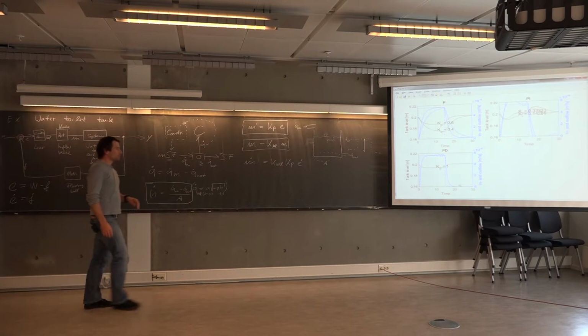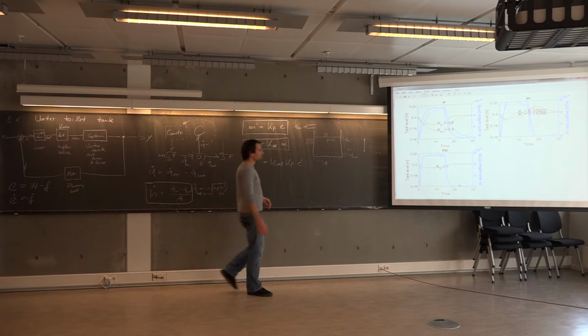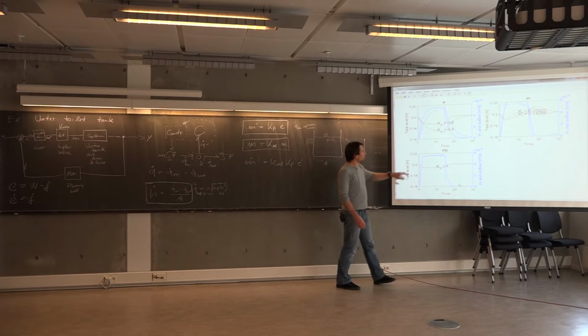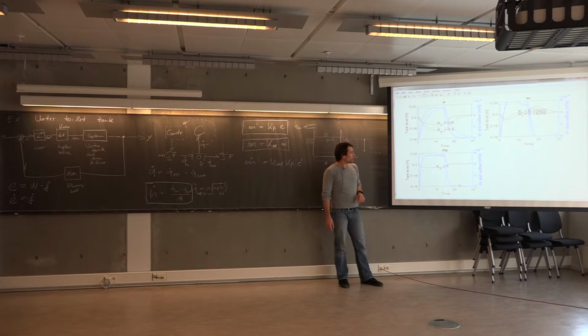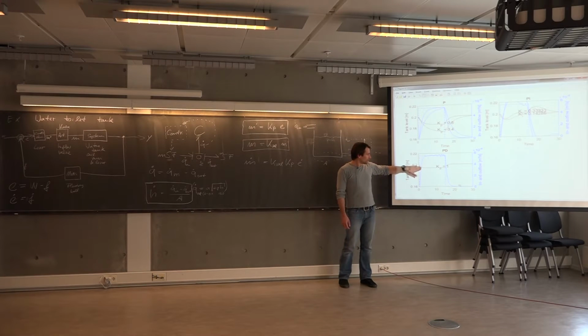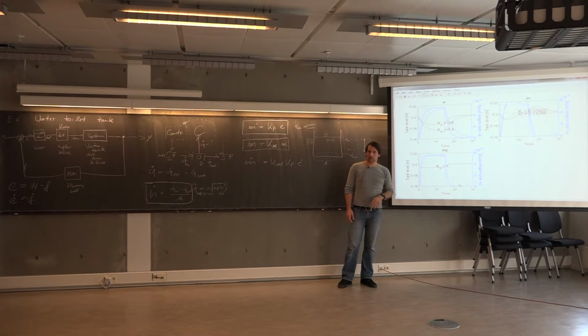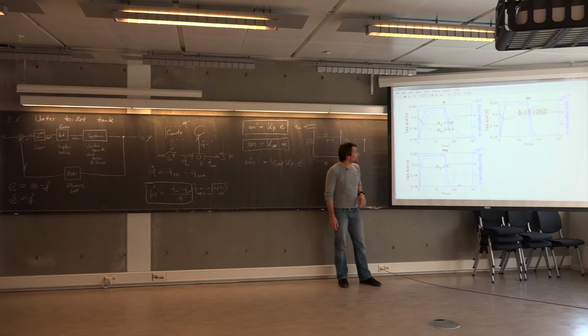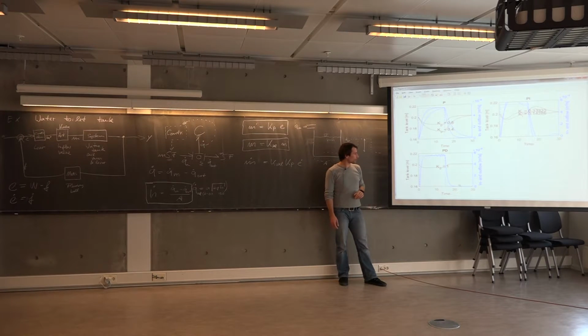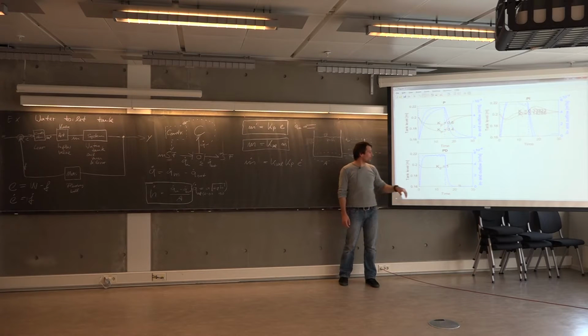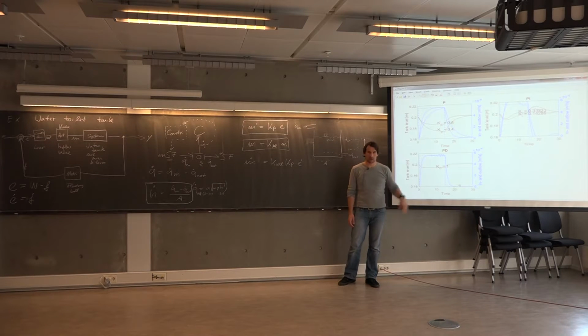If we use that control approach, meaning proportional and derivative control, then we may actually speed up the controller response and reach a steady state offset faster than with the pure proportional control approach. We still, though, have to live with some sort of offset, right?